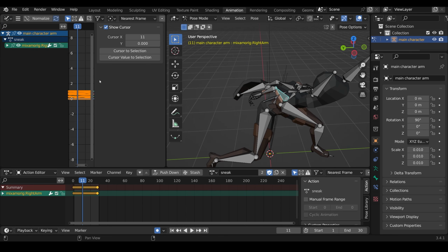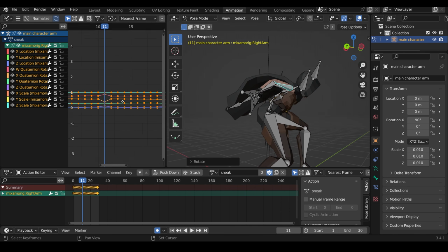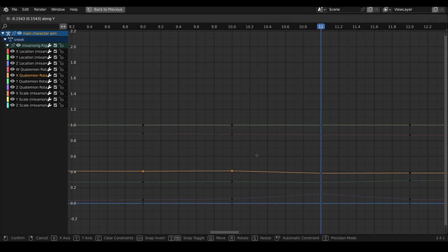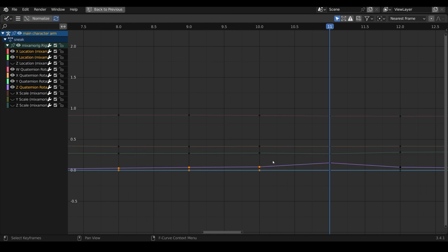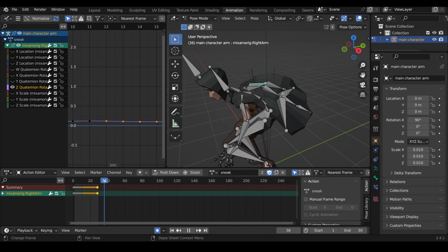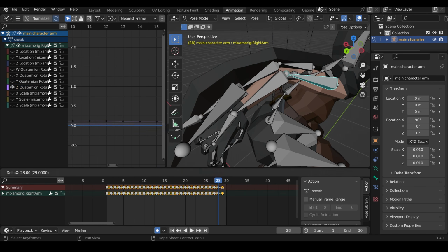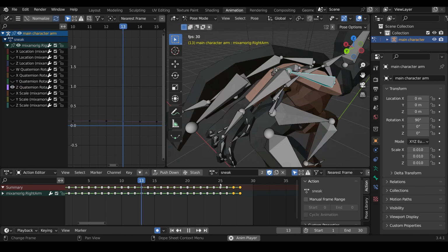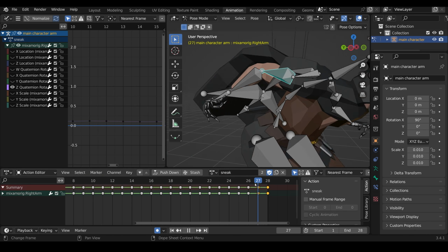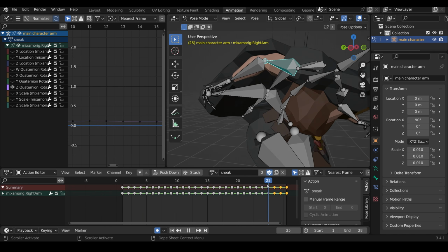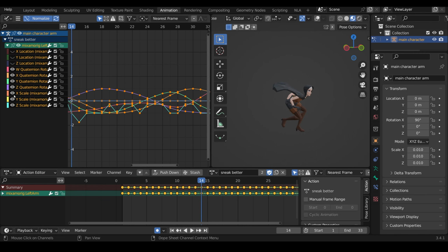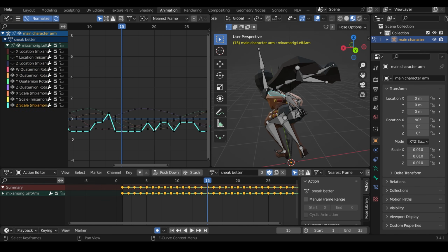Now to sort out those problem animations where the arms are a bit distorted, again, if anybody knows why that happens, let me know. I need to go into the graph editor and change the position of the arm. The reason I choose the graph editor is I change it in one position and then I look at the graph, see where the new position is, and then I can move the rest of the keyframes for that channel accordingly. For some reason it didn't work that well on this particular arm, and it was taking me a long time to try and fix a little jump that was there, but for the rest of the actions this worked perfectly. Again, this is something I could probably do another tutorial on, and if you want that kind of thing then let me know.